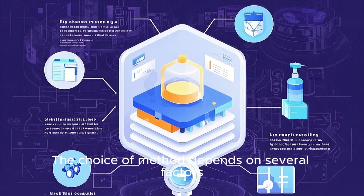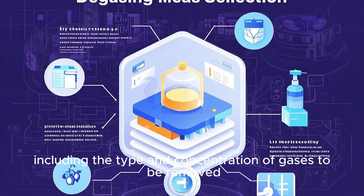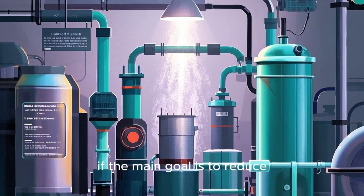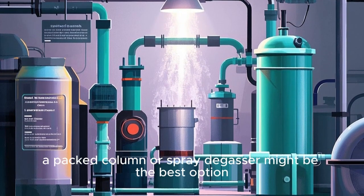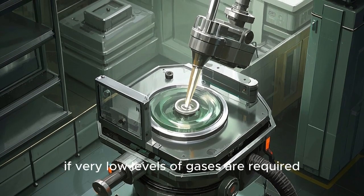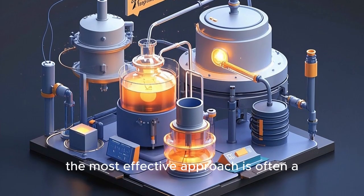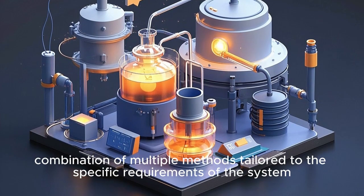The choice of method depends on several factors, including the type and concentration of gases to be removed, the flow rate of water, space constraints, and budget. For instance, if the main goal is to reduce CO2 levels in a large volume of water, a packed column or spray degasser might be the best option. On the other hand, if very low levels of gases are required, a vacuum degasser may be more suitable. Ultimately, the most effective approach is often a combination of multiple methods tailored to the specific requirements of the system.